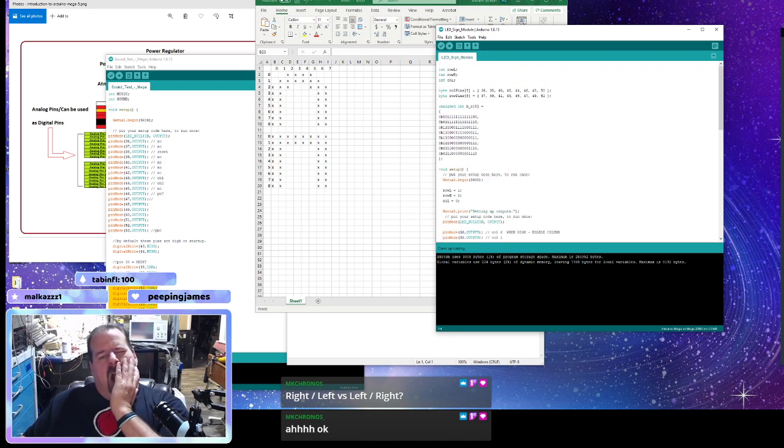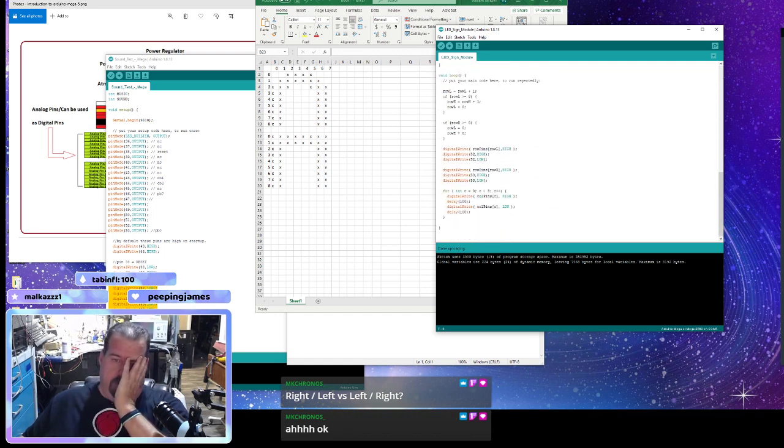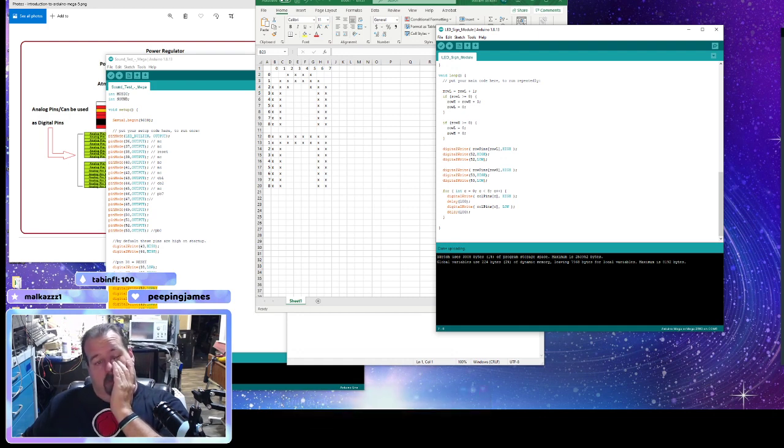So I wrote a function. We generated this, which then I can just simply call the pin number based on the value and turn it on high and low. But now I realize that if I need to turn on more than one bit, I need to check every bit and then update all the bits to be on, then latch it. So right here I'm latching. So right now I'm just checking this.